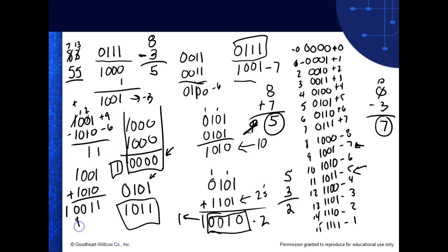We expected a positive answer, so the overflow flag would be a 0 because we added a positive and a negative number, and we came up with what we expected, a positive answer. And this right here would be the carry. Now, if this was unsigned, this would still be a 9, and this here would be a 10, which now gives me a 16. Well, I can't represent 16. So now I would be concerned with the what? The carry. So if I'm dealing with unsigned numbers, I'm going to be concerned with the carry.